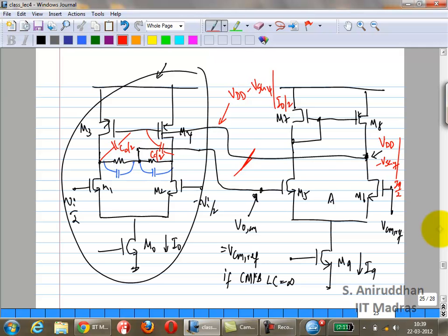Now, the value of CC, what happens if it's very large? Do you want to add extra margin? Let's say you had the option of making the unity gain frequency much lower. Would you do it? Well, you'll note that if you go back to the differential picture, CC actually loads the differential outputs. Okay, you definitely don't want to make CC very large, right? So you don't want to overcompensate the common mode feedback loop.